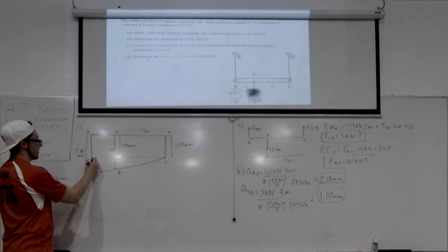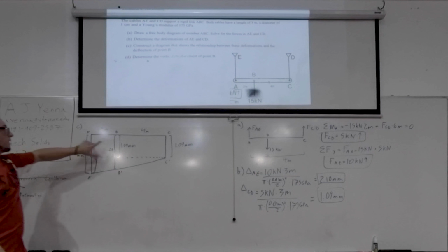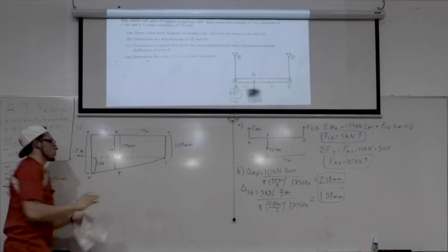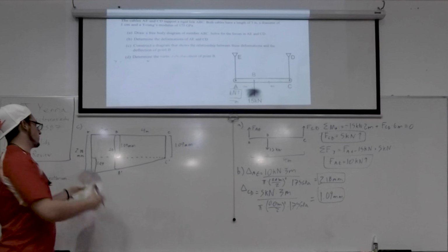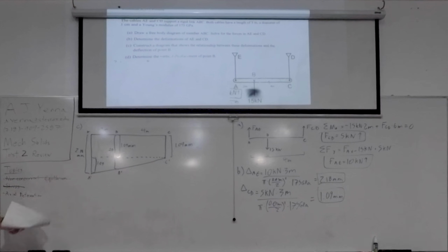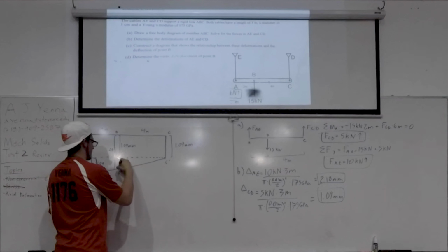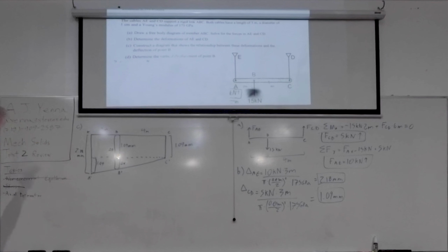We also know this distance here, because it is 2.18 minus 1.09, which comes out to 1.09. But these are all values that you could solve for geometrically. If you look at all the angles and the sides, you can conceptually figure out what all this is doing. The last thing we're missing in order to find delta B is this delta X value here. And that's your deformation diagram. So this is everything showing how far B moved. Anybody have a question about how I draw it, why I drew certain things? Everybody's clear on that? Okay.